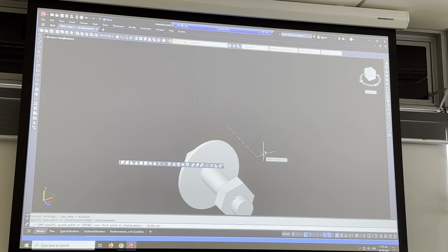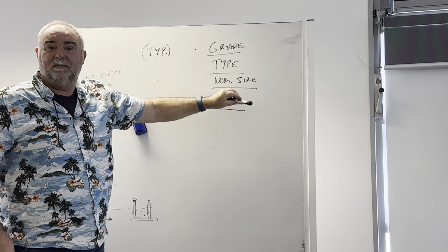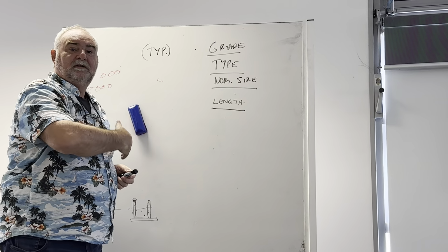Another way of doing it is to refer to the notes, and in your notes section say that all the timber is radiata pine of grade such and such, and so you've covered it in the notes section, but you refer to it. So you've got a few choices.